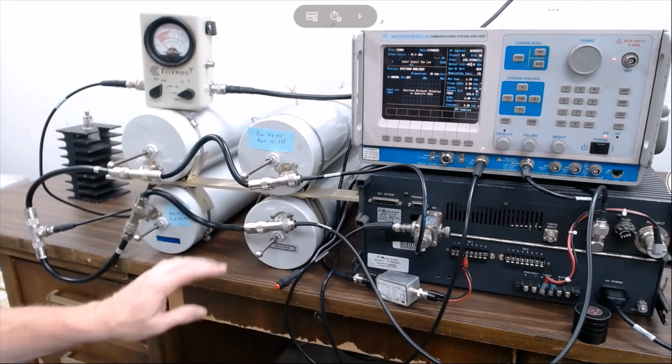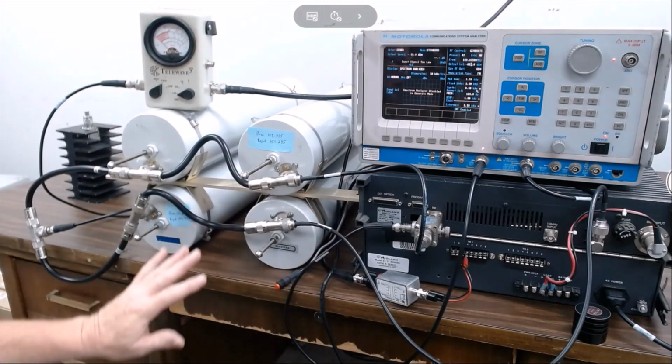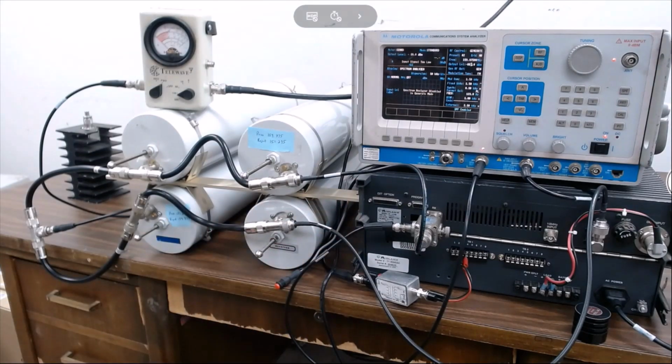The very final test after you put all the cables back into place is to do a radio check with your portable with dispatch. Make sure you have your antenna disconnected from your portable, and everything should be tuned to even with no antenna on. So this concludes your test procedures. Now I will go back in and look at the adjustments needed for each individual test.